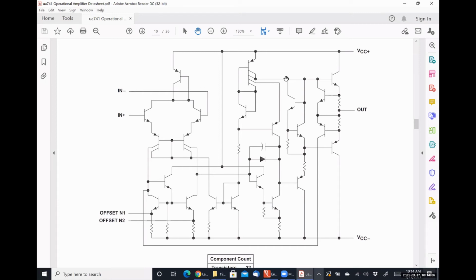There's circuitry in here specifically to be able to apply a small voltage to either pin 1 or pin 2. Typically, you would put a potentiometer between those two and, with a voltage on one of the legs, adjust the ratio of the resistances to zero out the offset on both of the pins simultaneously.